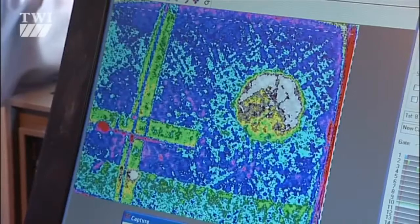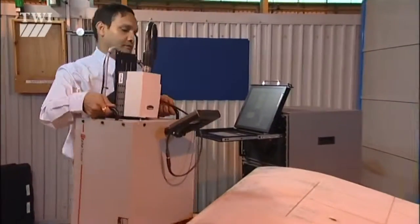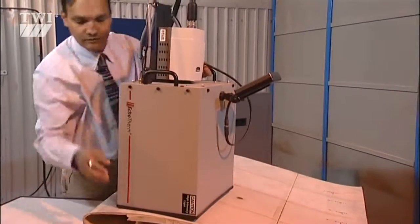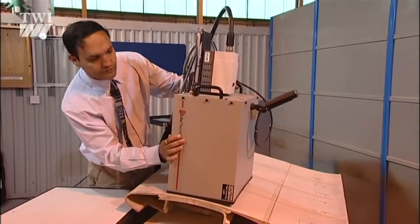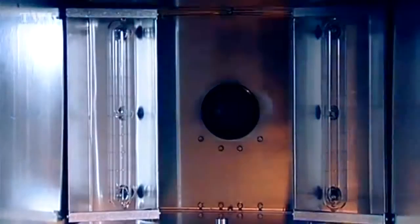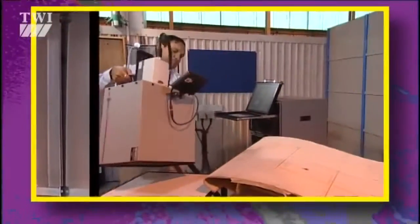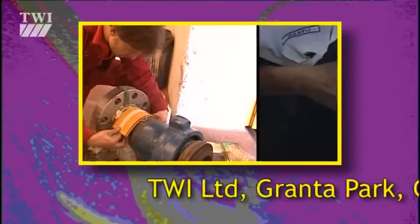Thermography is a remote technique for use in most areas of plant, but is particularly suited to equipment operating at elevated temperatures. Active thermography, where heat is applied directly to the component, is used for inspection of low conductivity materials, like composites. Well, thermography just about winds up this brief introduction to the popular non-destructive testing techniques.